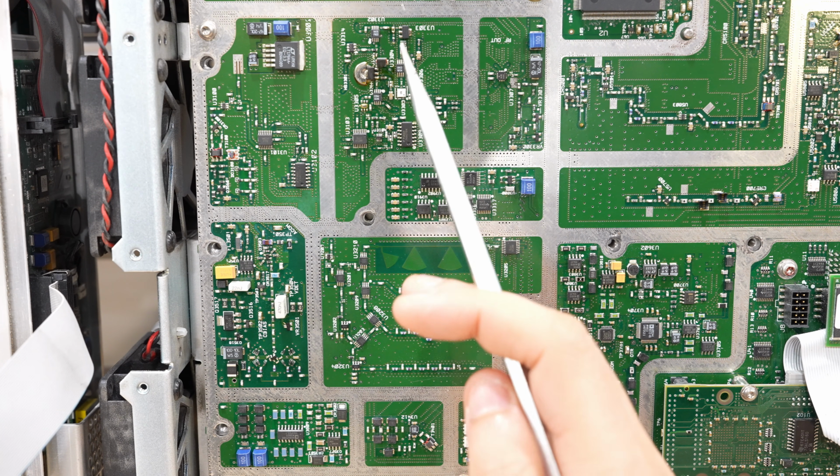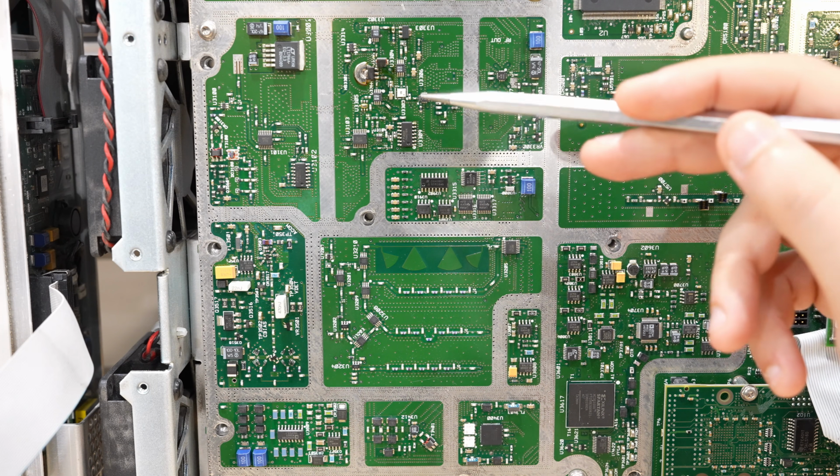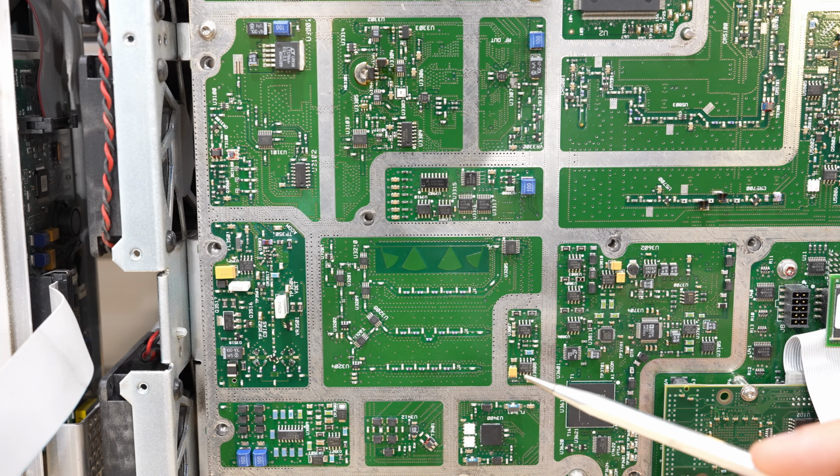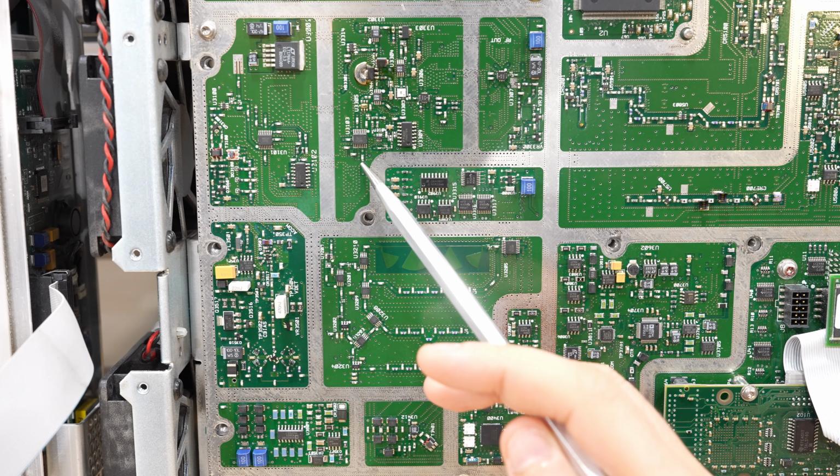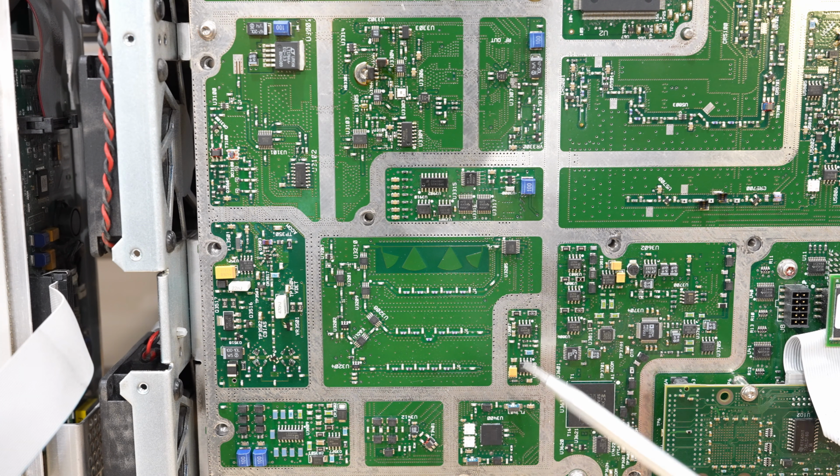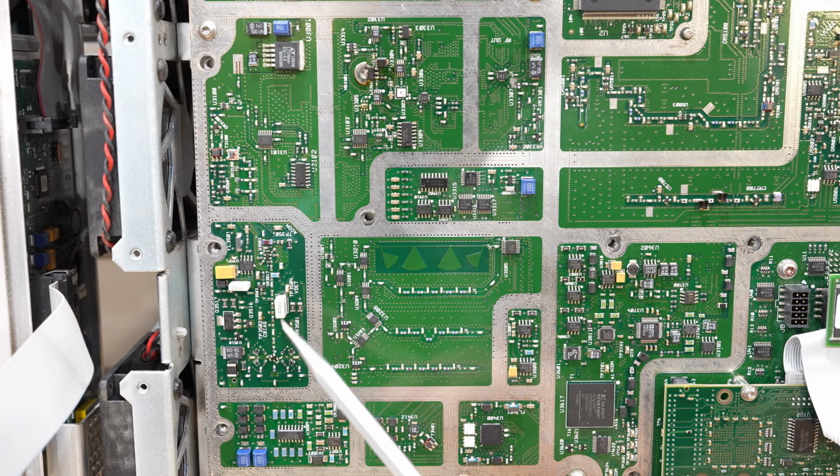And then it goes up here, and there is more multiplication. But we're not interested in the path going up anymore because that goes back into the actual RF output. Over here, there is the path outside of this, which then passes everything down into here. And this is our Fractional-N. It's a custom part by On Semiconductor, which is made for Keysight, I think. And then from this, it goes to the phase detector. The 50 megahertz input also reaches the phase detector, which we know works because that comes from all the way on the other side. So the 50 megahertz, that is the loop, closed loop 50 megahertz and the fixed 50 megahertz, both going to the phase detector and then comes back over here. And I think this op-amp is part of the integrator, which then controls the VCO.